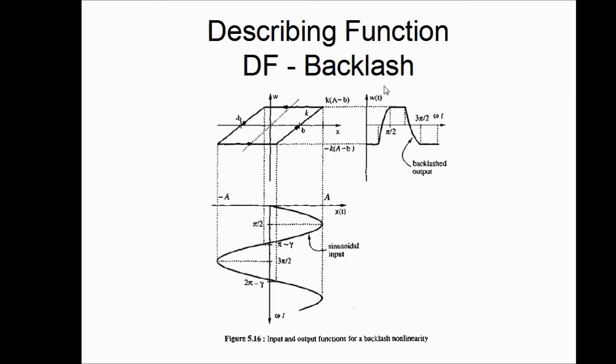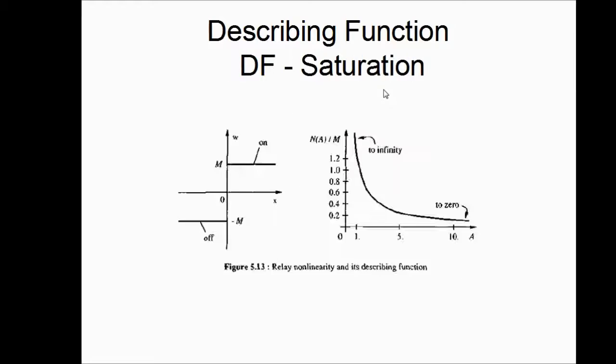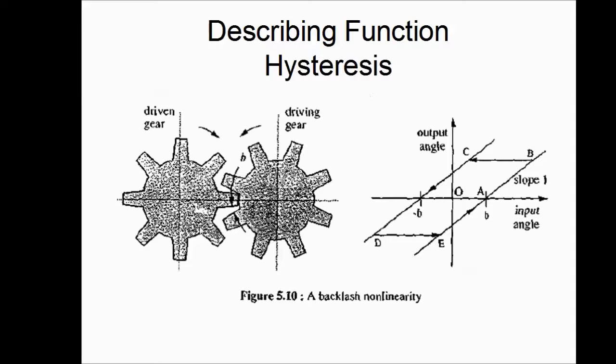Likewise, if we look at the backlash nonlinearity, backlash is caused by gears, like we previously described. Backlash is caused here when there is no action because of a little fault in the gear teeth. The driving teeth and driven teeth are incorrectly engaged for that small angle where there is a fault in the teeth, a deformation in the teeth due to overuse or some other reason. So this causes a hysteresis type of nonlinearity to manifest. So we need to study this nonlinearity now.